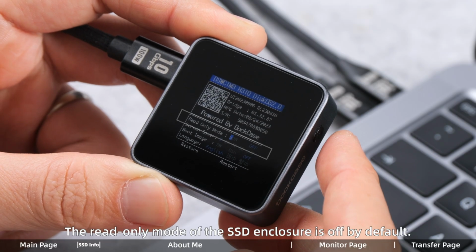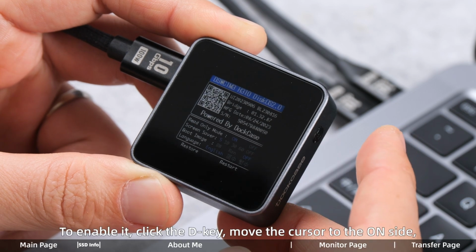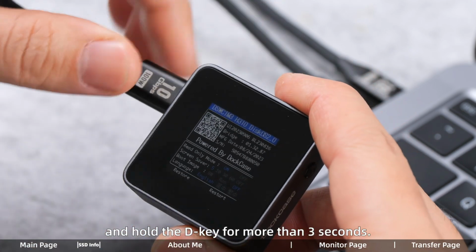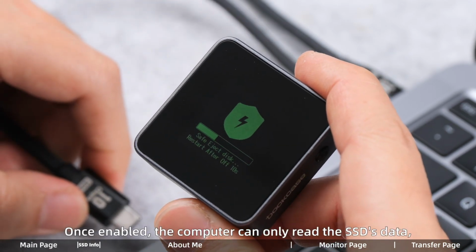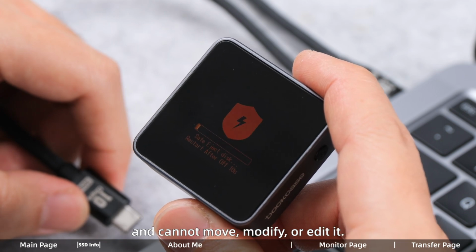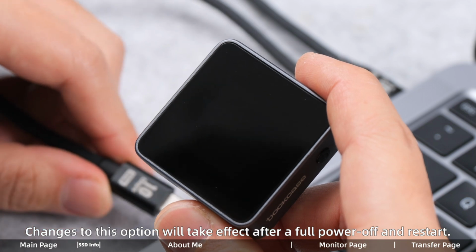Read-only mode. The read-only mode of the SSD enclosure is off by default. To enable it, click the D key, move the cursor to the on side, and hold the D key for more than 3 seconds. Once enabled, the computer can only read the SSD's data, and cannot move, modify, or edit it. Changes to this option will take effect after a full power off and restart.